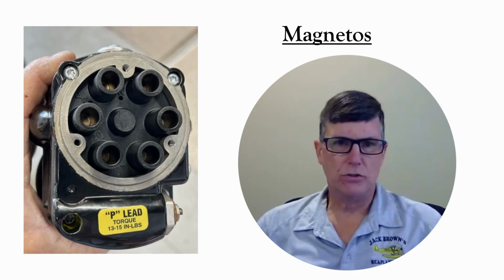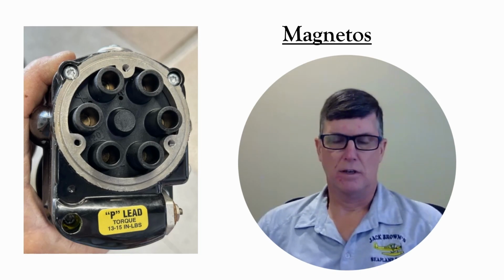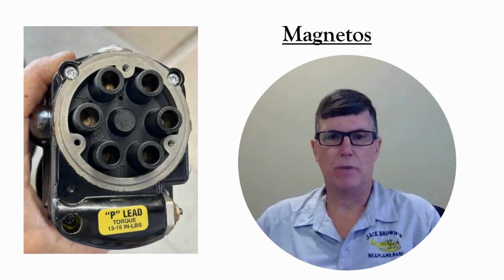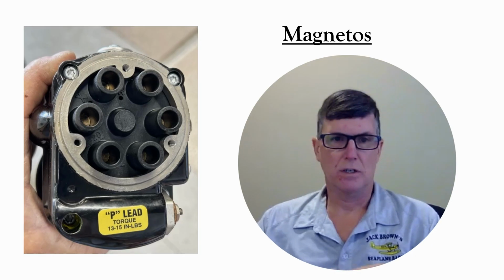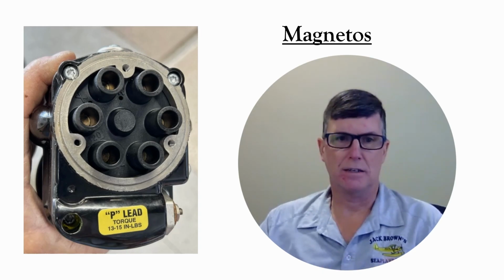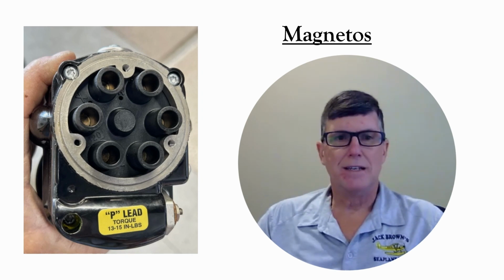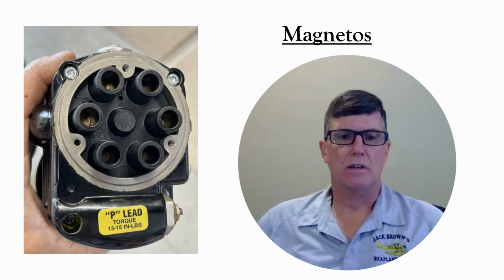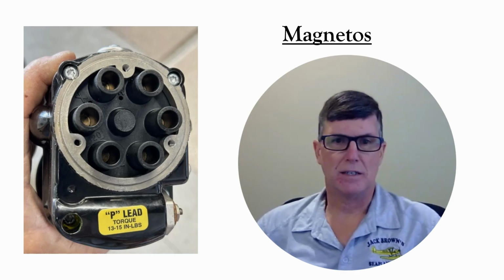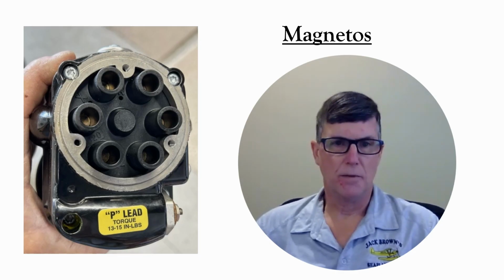Now, a unique feature of a magneto is how it's turned on and off. Unlike a typical light switch, which gets turned on by making an electrical connection, a magneto is actually turned on by breaking an electrical connection. In order to turn the magneto off, a thing called the P-lead on the magneto has to be connected to ground, which happens via the ignition switch.